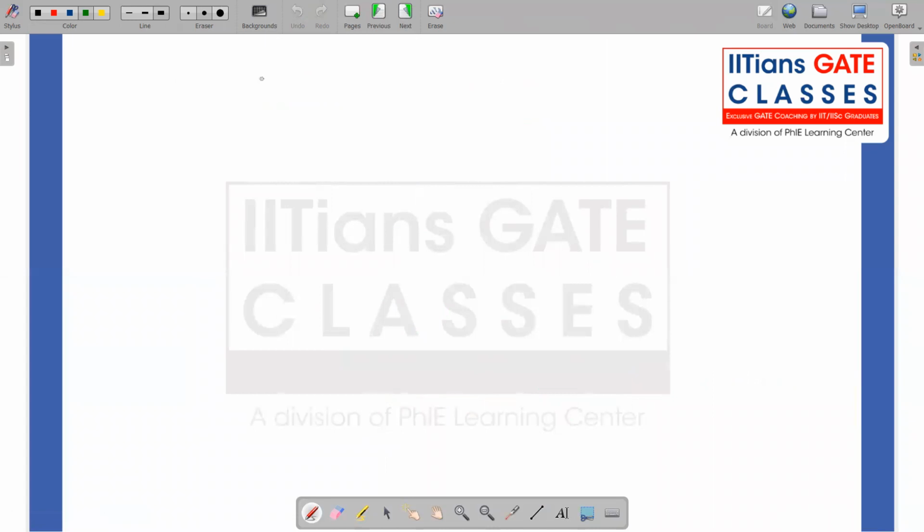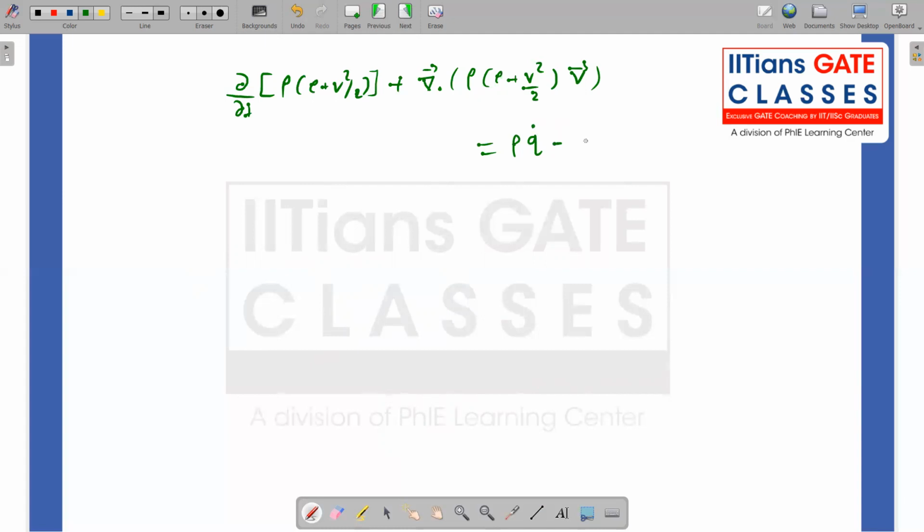That leaves me ∂/∂t of rho times (E plus V squared by 2), plus the divergence of rho times (E plus V squared by 2) times the velocity vector, equal to rho q dot minus the divergence of pressure times velocity, plus rho times f dot the velocity vector. This is my energy equation in differential form.